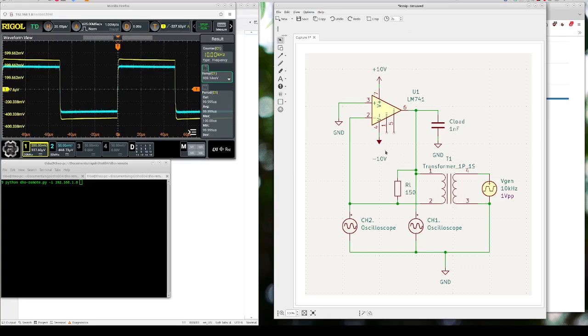And because of the high loop gain of this opamp, any signal that you try to put between the output and the input will develop at its output, because any signal at the input will be multiplied by the open loop gain of the opamp. And so any finite output signal will be a very tiny input signal. Now that's what we will show on the scope screen later.